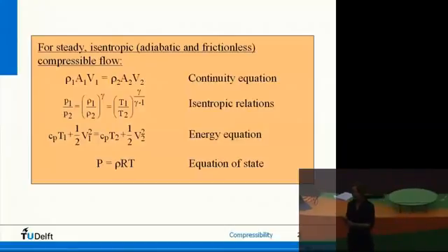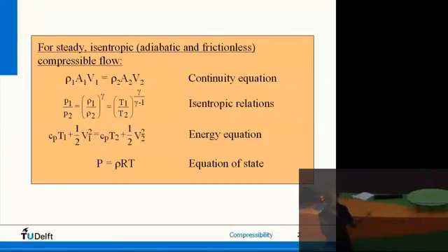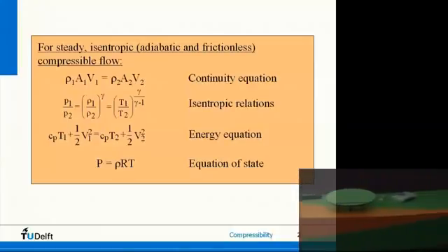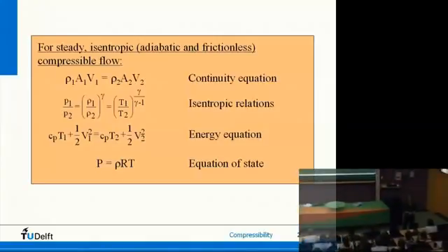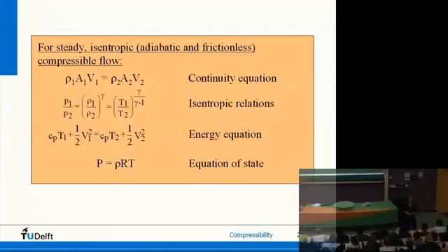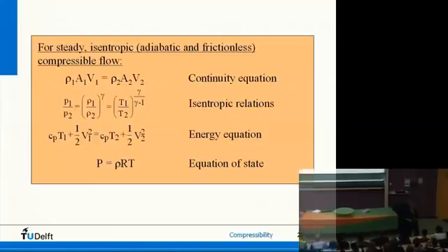And actually, if your flow is fast, supersonic, transonic, you have pressure and density changes such that the temperature does change in your flow, through P is rho RT. It can expand very much, for example, so the density can drop a lot, and then something will happen to the temperature as well. So please bear in mind, isentropic flow means there's no heat added or subtracted, but the temperature can change. And the other thing is that it should be reversible so that dissipative effects can be neglected.